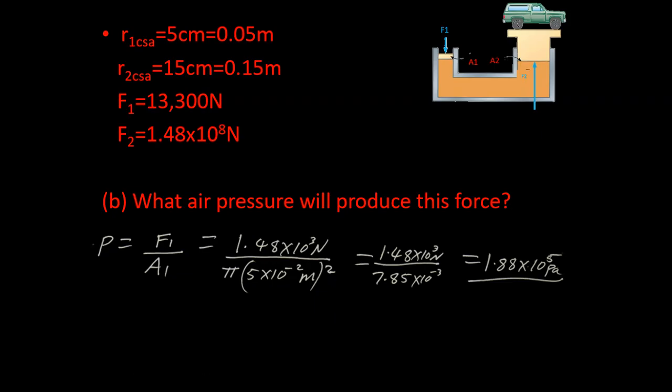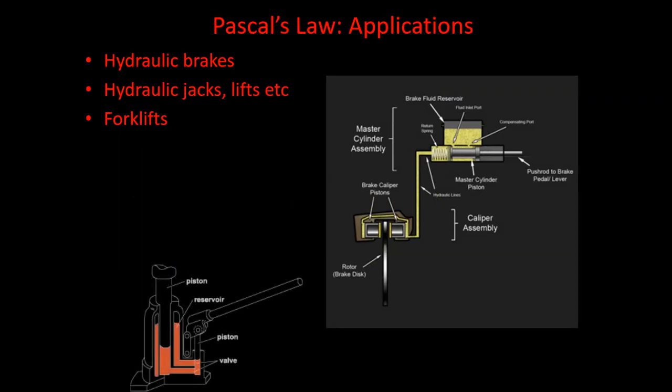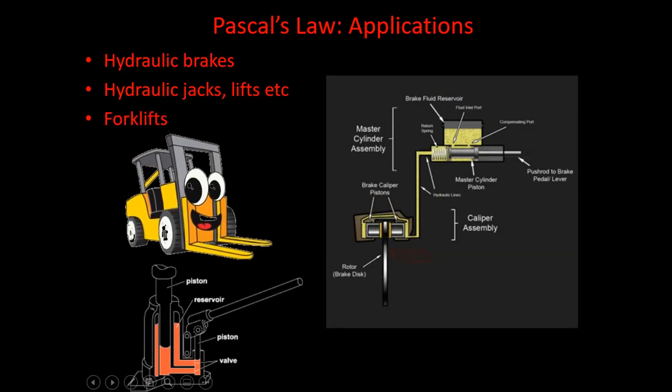And Pascal's law has many, many applications. Hydraulic brakes, for one, anywhere where you are trying to translate a force around a corner. Here's a brake system. If you have this end attached to your brakes, you push the pedal here and this will push this cylinder, and that will use Pascal's law to increase the force at this end of the brake and push these pistons with a greater amount of force to squeeze the rotor and slow down your wheels. So this is basically how brakes will apply a greater force at this end than you're putting in with your foot.